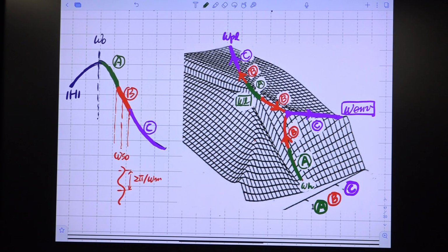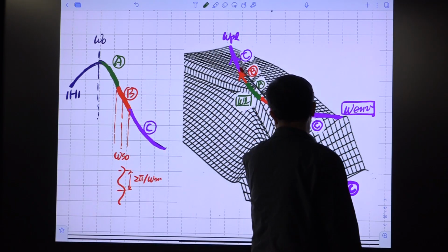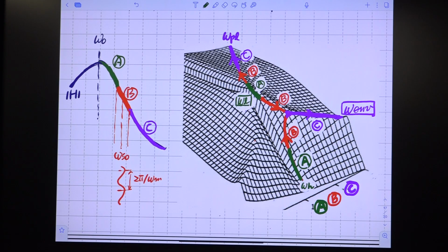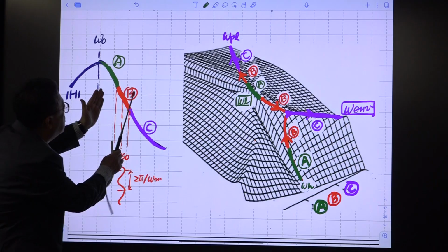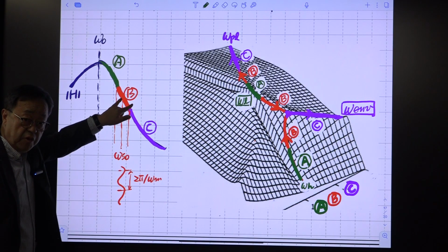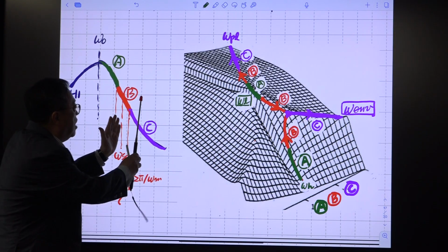Okay? And I have seen so many cases. They all fall into one of these categories. Okay? Maybe one point is somewhere here, somewhere here, somewhere here. All right? So using this is very important. Okay? Then with this, you can identify the worst case dynamics when your switching frequency is varied over a frequency range. Okay? Suppose your switching frequency in your previous test is limited here, then you have only 3 dual poles. Okay? If the switching frequency range covers here, in some region you have 3 dual poles,